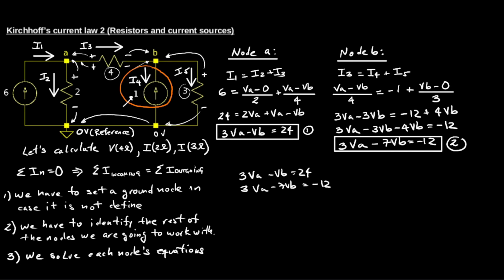is the voltages in the different nodes of the circuit. Okay, in this case, as I said, we have 3 nodes, one known node, which is the reference node, whose voltage is 0 because it is my ground node, my reference node, and from these two equations, I'm going to get the voltages in the nodes, and from these voltages in these nodes, I'm going to get the different currents I want.